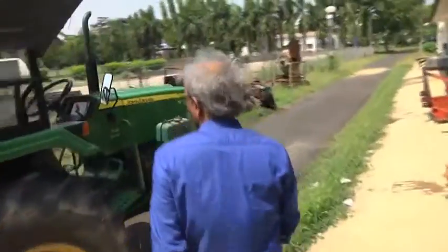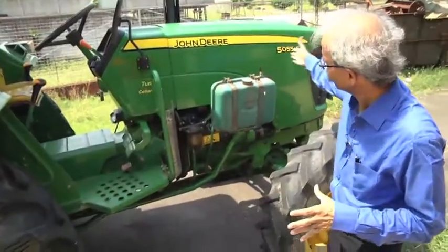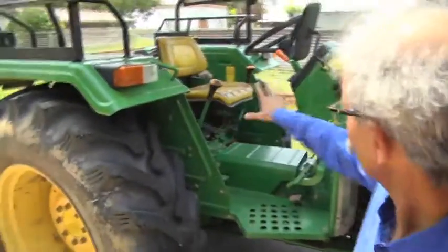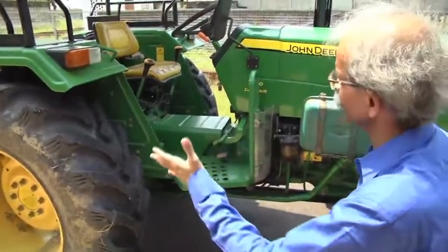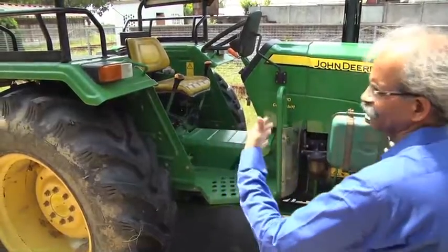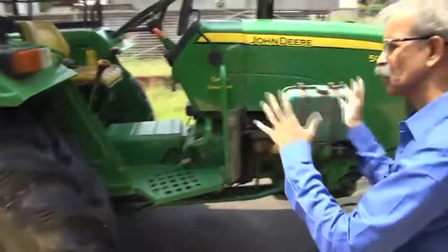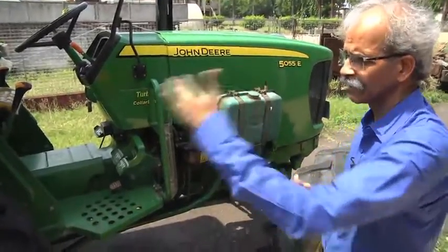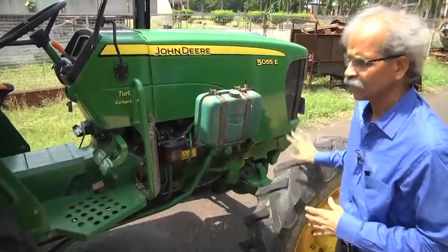Now, you see the weight distribution of the present tractor. We can see here right from here is our radiator, and then the engine, the transmission, then differential and final drive. All these are well distributed. It is a 4-wheel drive tractor. Generally, when we have a 4-wheel drive tractor, we will have the weight distribution approximately on the front axle and rear axle approximately 50-50. But when we have a 2-wheel drive, as we have in other tractors, we have about 65 to 70% of the weight on the rear axle and about 30-35% weight on the front axle. But this is a 4 wheel drive tractor.